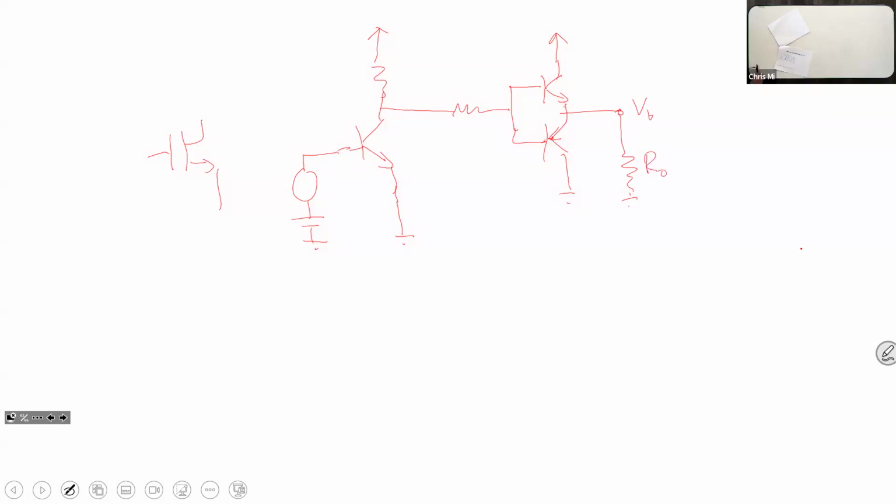So now we're going to link this together with this circuit. You see, I have a two-stage amplifier. The first stage is a small signal amplifier. I will explain a little bit further. But the second stage is a power amplifier. What I'm doing here is, from the first stage, I amplify a very small signal to a certain value so that it's usable. But still, it's a signal. It does not have power, it cannot drive anything. But on the second stage, I will be able to drive, let's say, a speaker or a relay or something with much more current available.